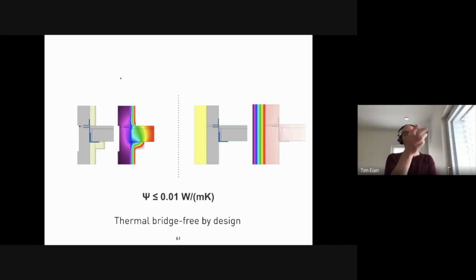We actually showed the owner that the whole perimeter in the winter, that interior floor slab will be at frost temperature, and that's in conditioned space. So by taking the same insulation that they had on the inside of the building and flipping it around, putting it on the outside, you can see the isotherms on the right-hand side. You forgo any thermal bridging whatsoever. So in this case, that doesn't really cost any money. It's just a different way of thinking about the same thing.